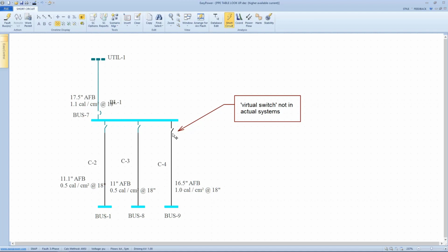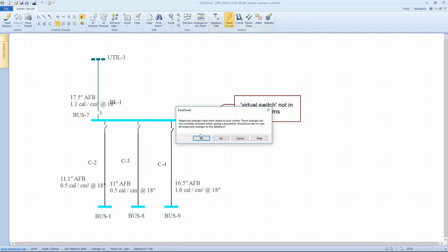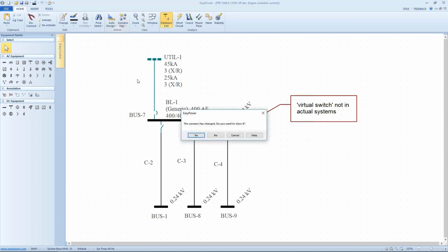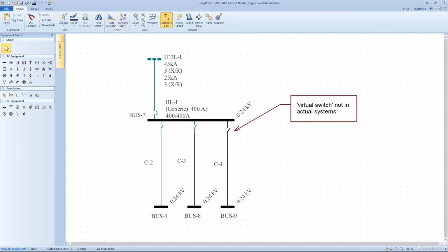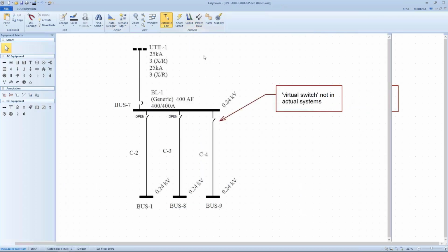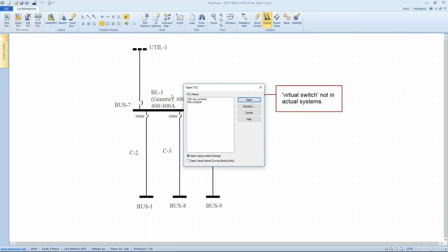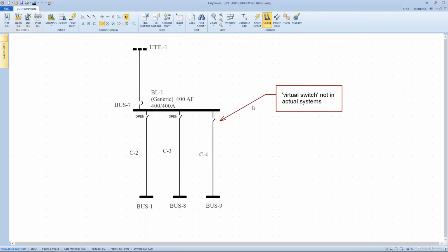So the high end of the current range wasn't a problem as long as the molded case circuit breaker operated normally. So the real consideration was how to ensure that we have the molded case circuit breaker operate in the instantaneous range. And to do that, let's go back to our base case, go into coordination, and we actually have already set up a plot for this.